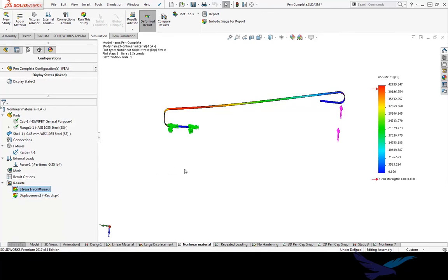But when we go to stress, you see that my max stress now is really close to the yield strength of the material defined. So already we're seeing a difference in terms of the overall results. We're getting a more realistic, or a more accurate, I should say, result with the nonlinear because we're now accounting for those assumptions that we couldn't do in a linear static. A large deformation, being able to see what happens post yield. So now my results are more accurate compared to that linear static study. Right? You see that the max stress is closer to that yield point there.